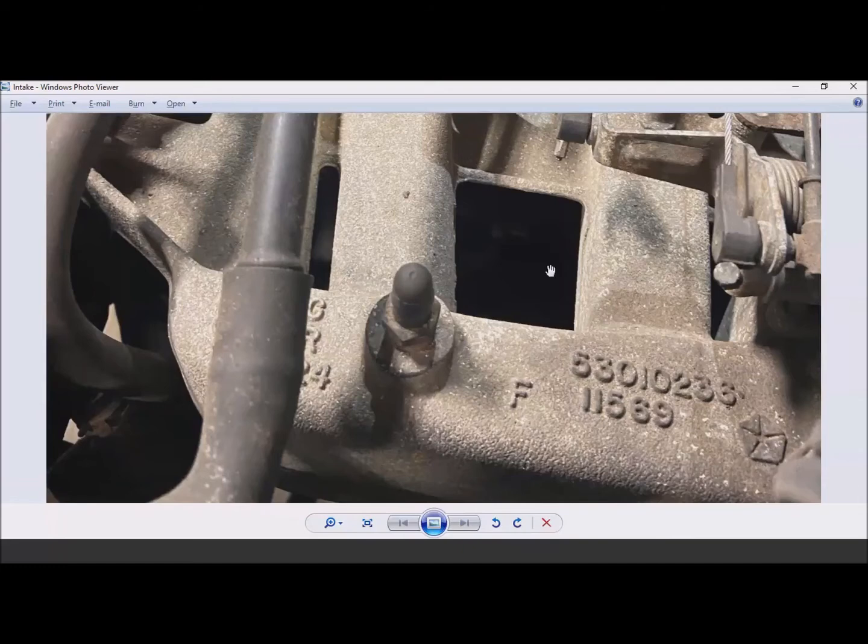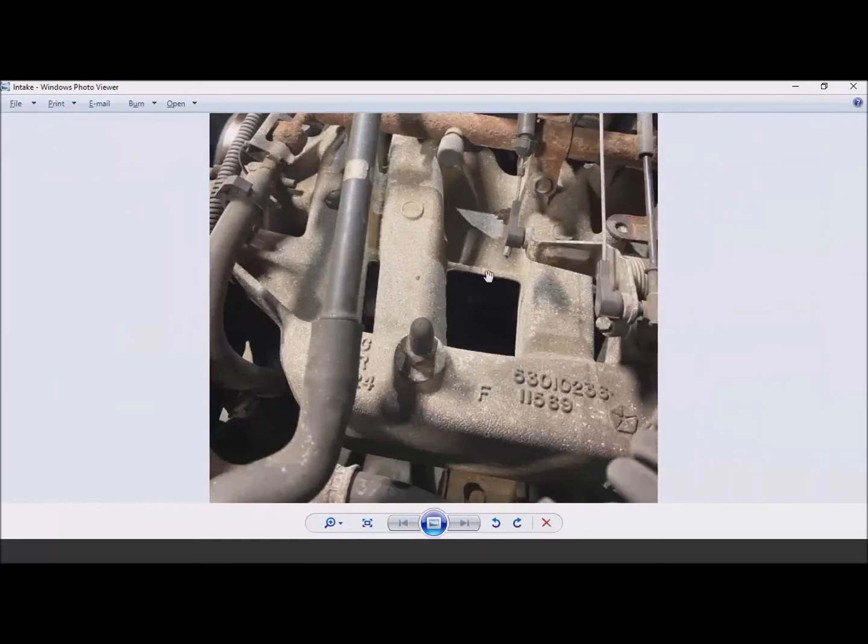Now, never mind that, rather than bringing the car to us for a tune-up, he tried to save money by bringing it somewhere else. Okay, whatever, we asked him, before we put an engine in your car, do you mind if we just look at it ourselves? And he said, no, go ahead. So almost immediately what we noticed, that there was a setup similar to this. It was a straight 6, and there was a vacuum hose. So it wasn't capped off. It was a vacuum hose that went to somewhere, but it was on one of the intake runners.